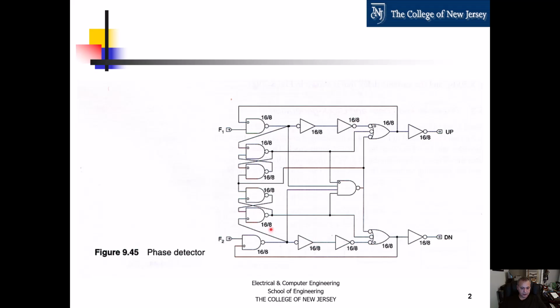So these transistors, let's take this gate here. Both the P channel and the N channel are going to be minimum width transistors or minimum channel length transistors, which for the technology that we have been using is 150 nanometers.